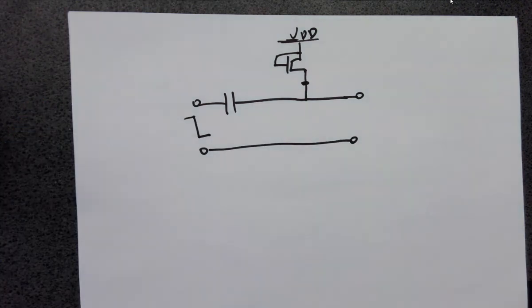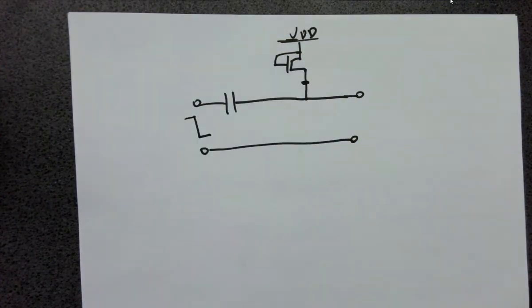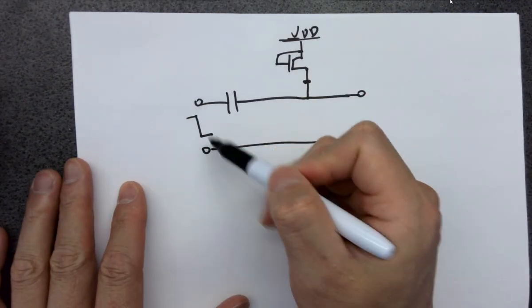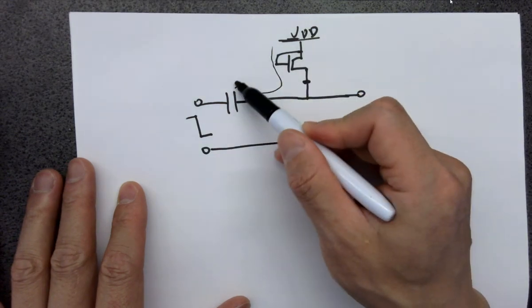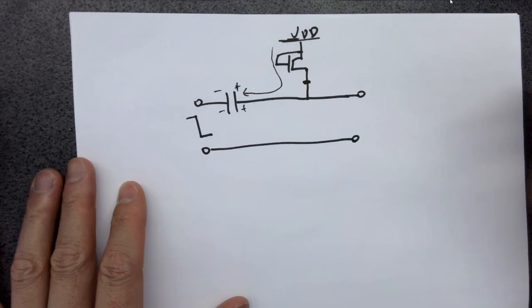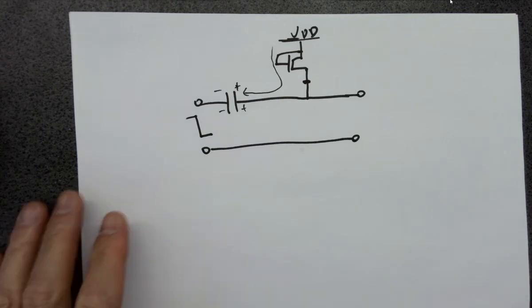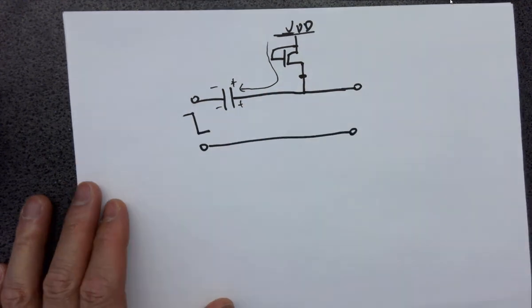So after today's lecture, if you can understand this one as a takeaway, I'll be really happy. Even though it's really simple, you have to form a model in your mind. So when this is pulling, keep in mind, it's dumping charges to the cap. If you don't understand why, I'm telling you it's going to happen, like what I said on page 2. So it's going to pull charges down. It's like grounding it, but only happening at the ramp.